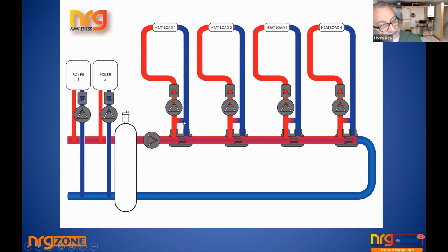Then when the water is passing in these bypasses, the pump can take it and heat the zone, or not take it, and it just carries on the same as before. So in that situation, that's fine. But again, you do have a lot of resistance on the pumps that you might not necessarily need.